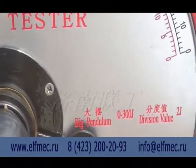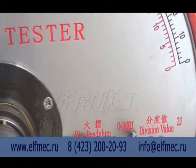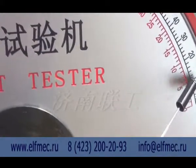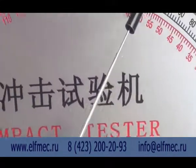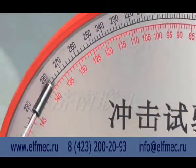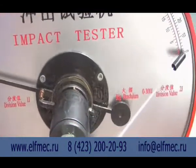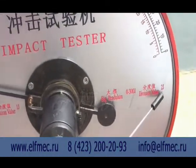Dial reading mode of the big pendulum. Confirm the single dividing range of the big pendulum on the dial. The handle drawn in black within the single line is used to read the energy value, and the energy value is read from right to left. The pointer indicates that the energy value rotates from left to right.